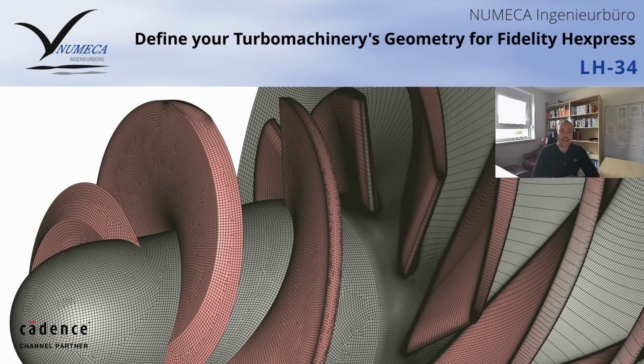My name is Patrick and today I would like to show you a feature in Fidelity that will simplify your workflow to create an unstructured mesh for your turbo machine. Of course, for turbo machines we usually have Autogrid. However, there are certain types of machine configurations that will make creating an unstructured grid a little bit difficult. I will show you a way today how you can set up your turbo machine geometry in Fidelity and then automatically create a watertight domain that you can use to create an unstructured grid in Hexpress.